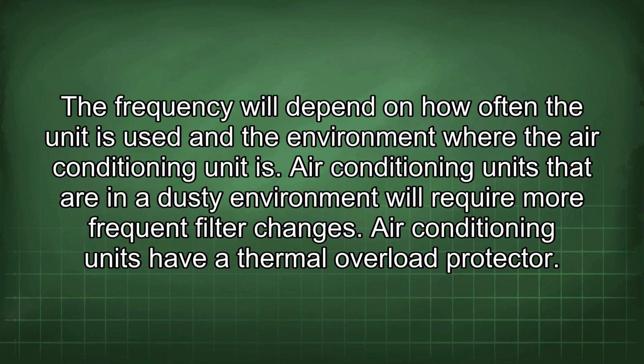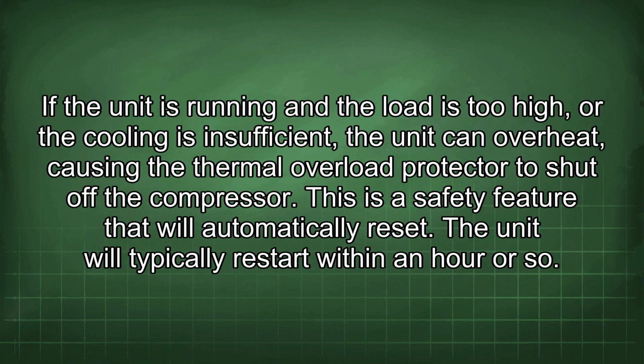Air conditioning units have a thermal overload protector. If the unit is running and the load is too high or the cooling is insufficient, the unit can overheat, causing the thermal overload protector to shut off the compressor. This is a safety feature that will automatically reset. The unit will typically restart within an hour or so.